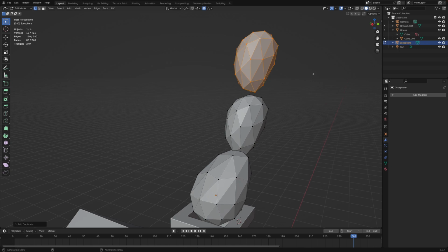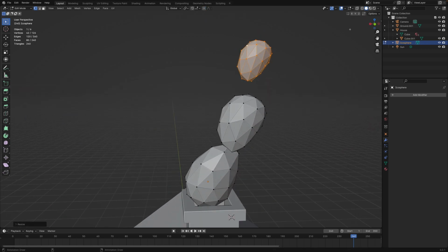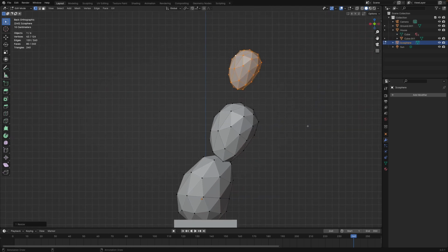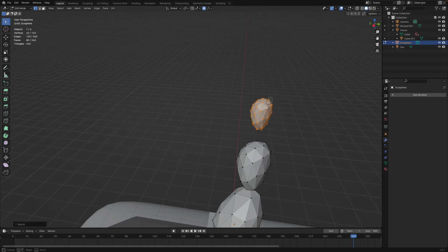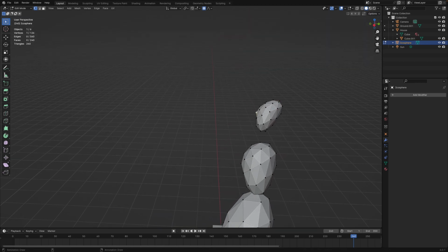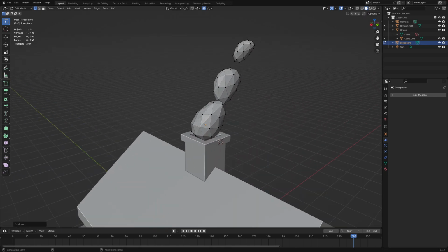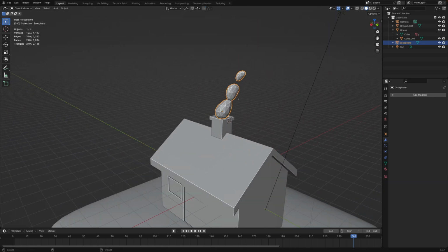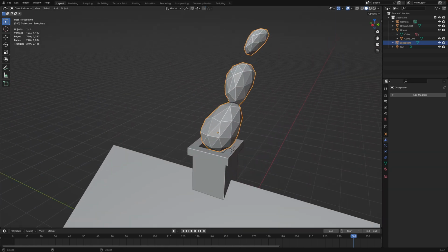S to scale, turn off proportional editing, S, side view, R, turn on proportional editing and do some adjustments. Okay, you can put in some more effort and time into this smoke if you want to. I'm out in object mode again now.